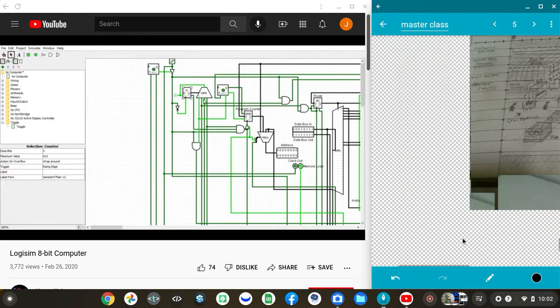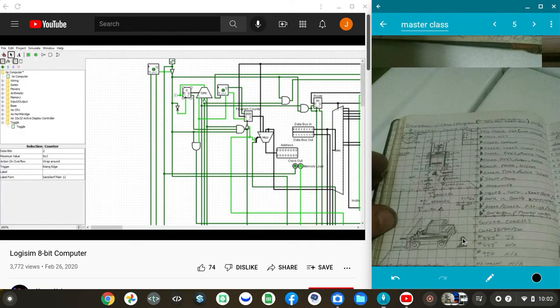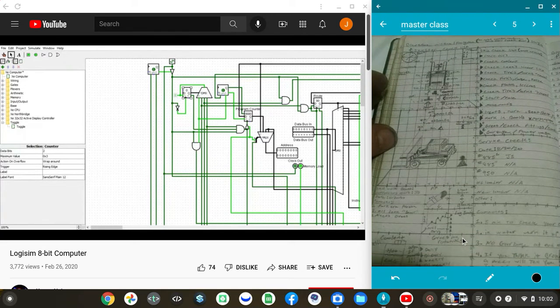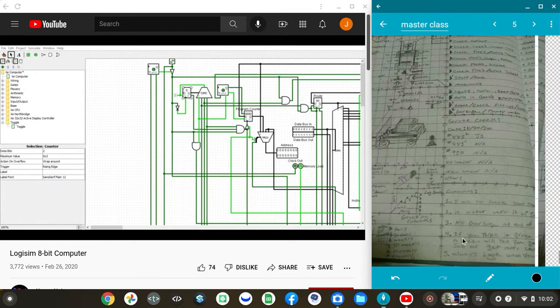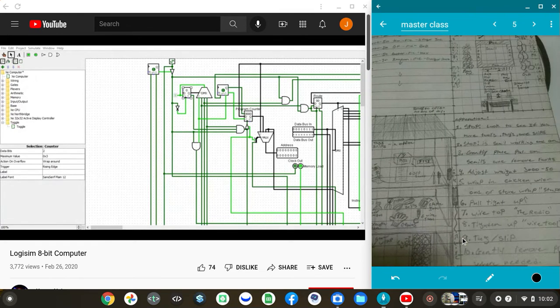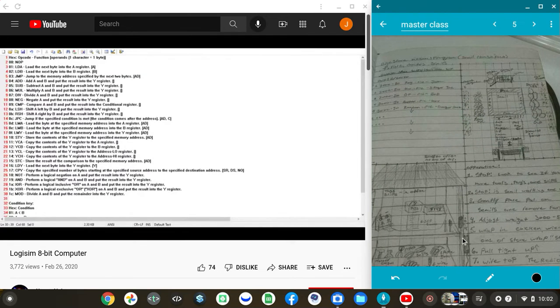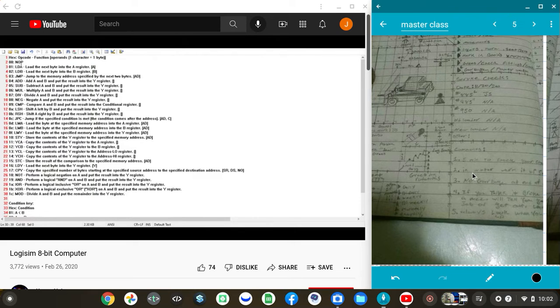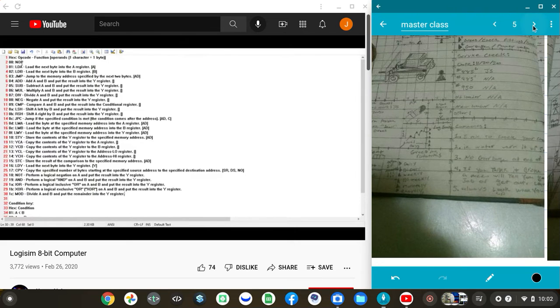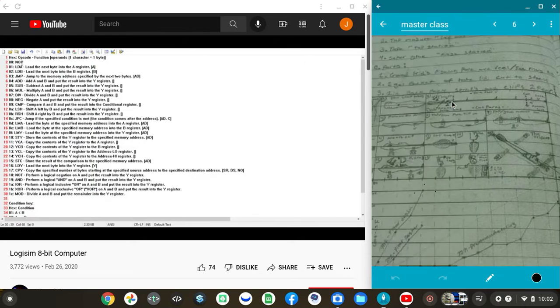Some examples of instructions that only take one cycle to complete, and I should probably show you the instruction set architecture, which is basically the instructions that the CPU knows. If I look at this, we've got these 29 instructions. And this NOP, which stands for no operation, it takes one cycle because there's nothing that it has to do.